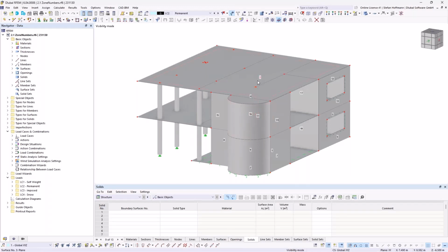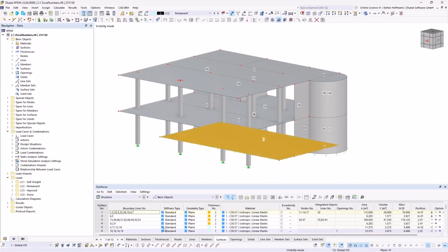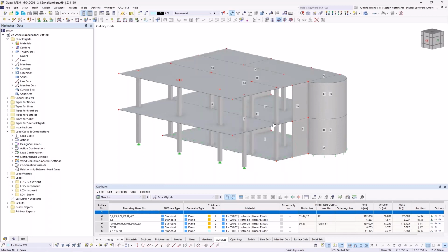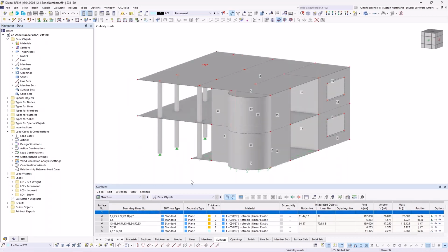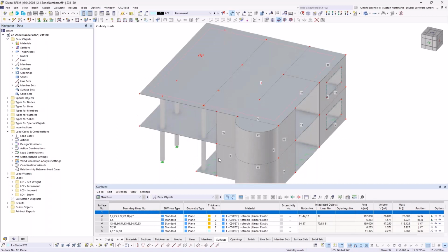on the surface numbers. You can see that we have a surface number 1. And if you do not want 1 to also include the member triangles, you just have to go into the table once and insert a row. So the surfaces will not start with 1, and all other things should be synchronized in the back. And now we have only surface numbers starting from 2, and all other stuff may be handed over to zone 1. If this is not fine enough for your purposes, we will also see it in the main example later on.